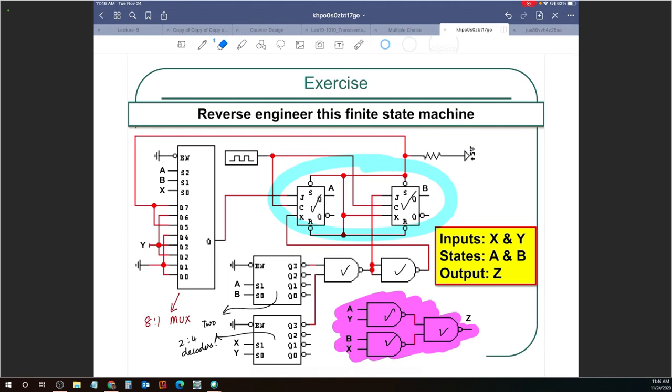So you have got an 8:1 mux, and we know how to write an equation for the output there in terms of its inputs. In this case, A, B, X are my select lines, and D7 all the way to D0 are my data inputs. So it's selecting one from all the others. Looking at this circuit, is it okay to have no idea what its function is? Absolutely. If you did know, then you have a very, very special skill. I don't know what it is doing right now.